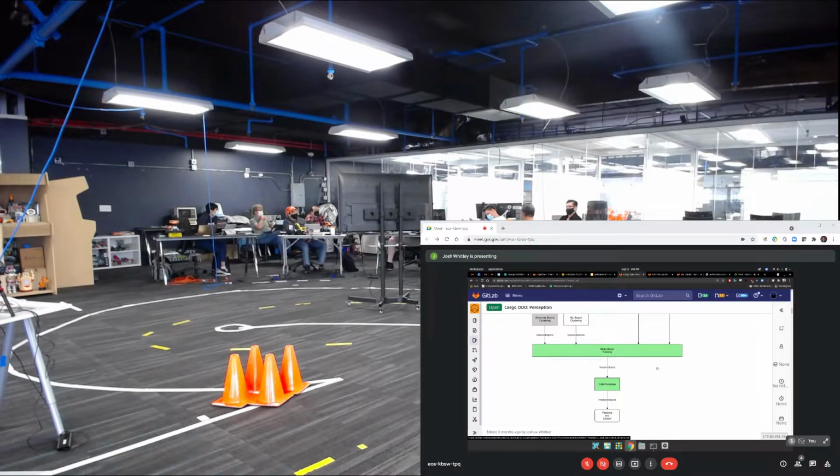And then if the objects are not moving, does it work really well? Yeah, it still works if they're not moving. It doesn't work as well for cross-track movement. If the object is moving toward you or away from you, it's very accurate. If it's moving through the radar array, it has a harder time detecting that unless it's moving pretty quickly. And then there are some radars like Smart Micro, which actually have a two-dimensional radar array, so they can discriminate in vertical and horizontal. But they're fairly new.